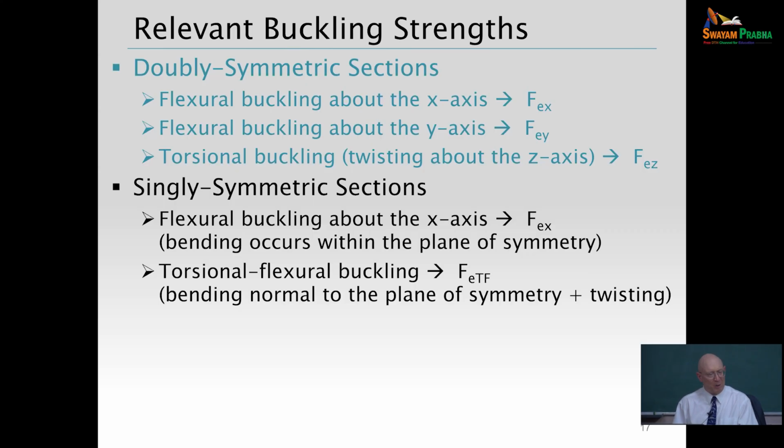But then you'd have to be holding it. Now, the holding it in that case would make it stronger. If we're not doing that, that would be rather elaborate to be able to do that. Then when it buckles by flexing and twisting, it's a smaller stress than what we would have by just flexural buckling about the minor axis, the y-axis.